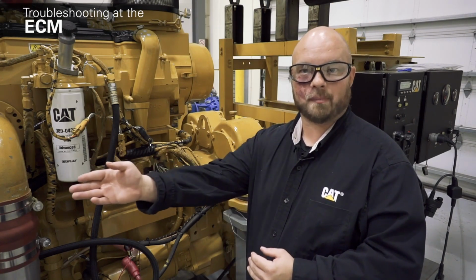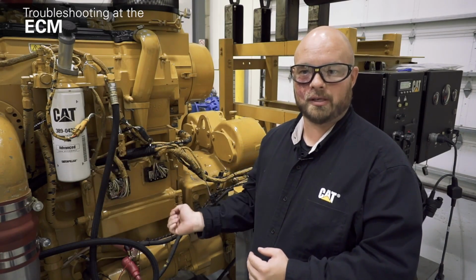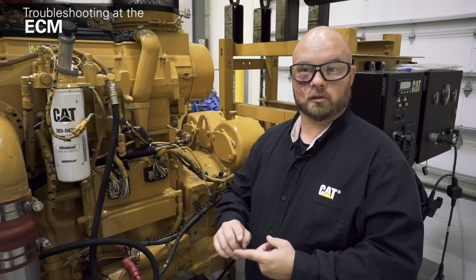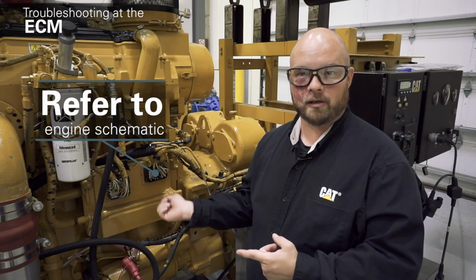So we made the opposite condition out at the harness with the sensor not installed. We're going to use that exact same logic, only now we're going to do that at the ECM. So first thing I need to do is look up the schematic for my engine here, okay? We need to find out where our signal wire from the sensor enters into the ECM. Which connector, which wire do we go at?